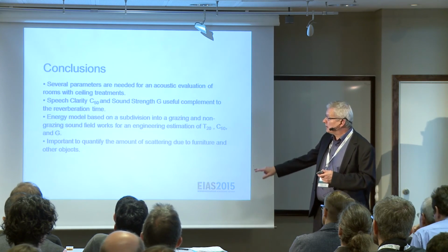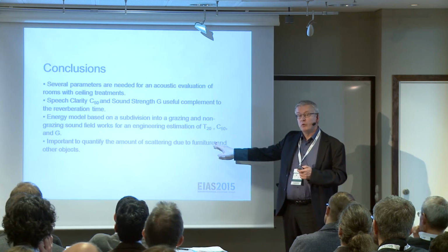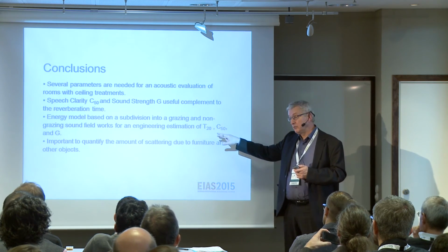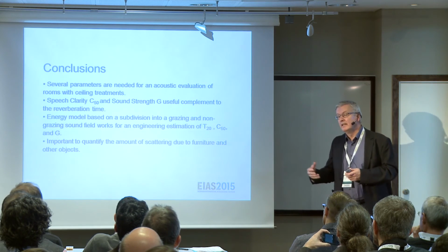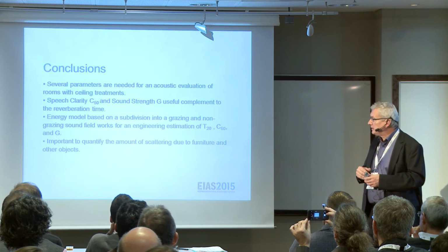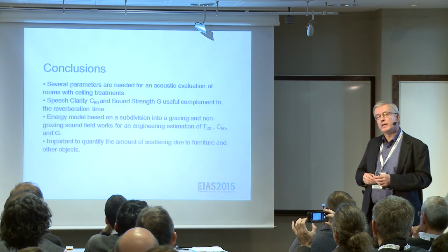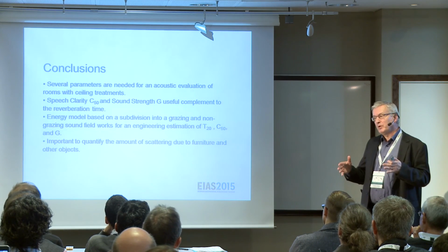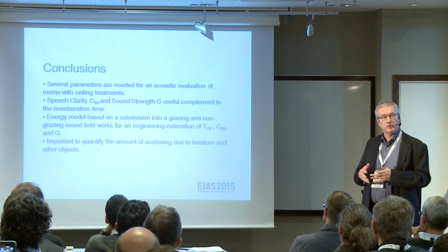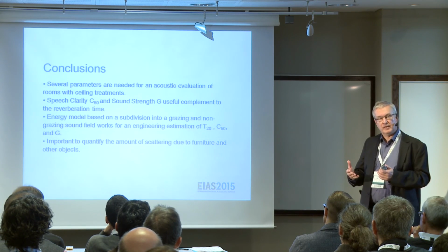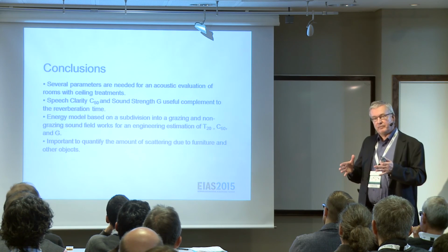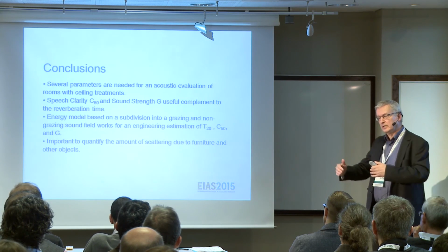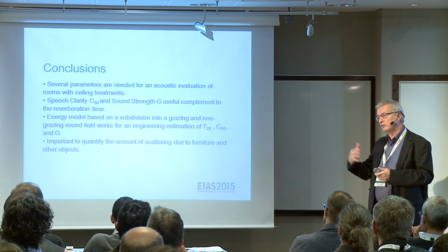And for engineering purposes, I think this subdivision into grazing and non-grazing works quite well. But what is quite important is that we have a method to quantify the scattering of furniture. And the way I did it here is quite simple. I think sometimes in standards it could be good to have methods that are quite close to reality. I mean, we have this ISO 354 standard where we measure the absorption coefficient, but that's quite special conditions. It's a diffuse field, there are reflectors, it's a small area. It differs quite a lot from what we have in practice.